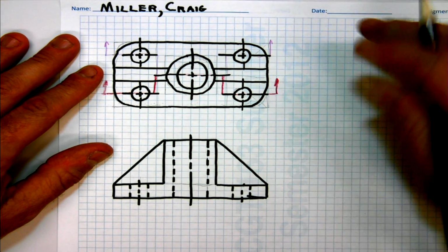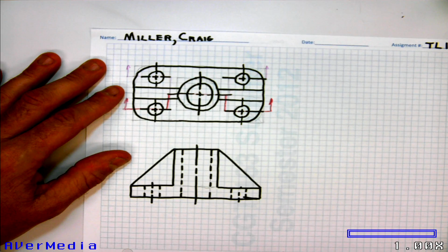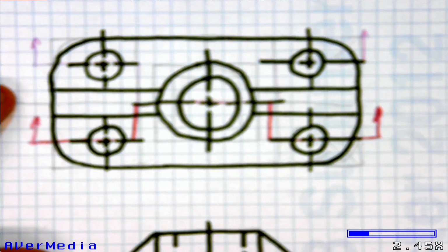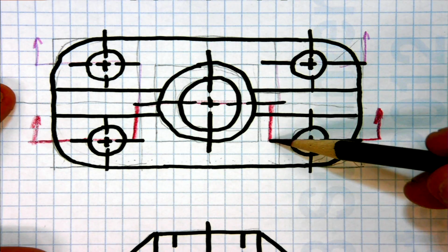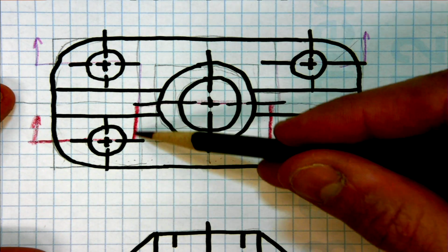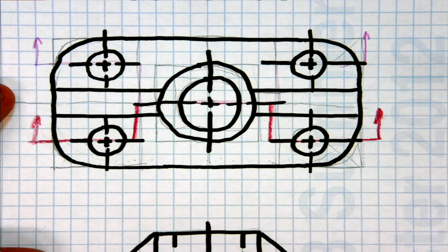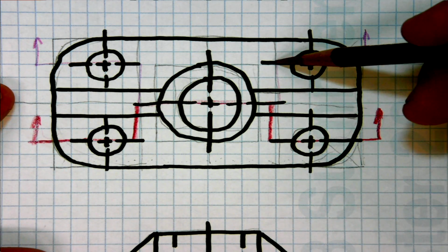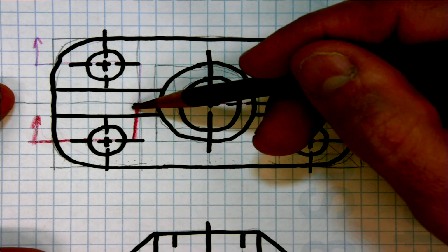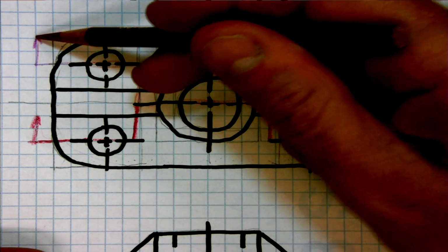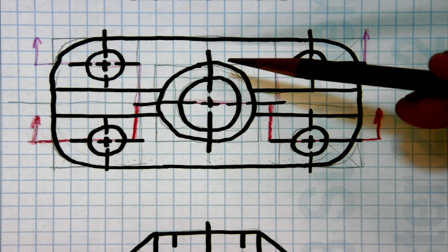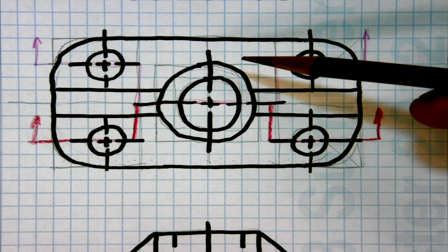Now you're going to get two radically different answers to this problem if you do this. So I'm going to zoom up here again so you can see the way I put these cutting planes. The red one goes here, turns, goes through the cylinders, turns, goes through here. Then the purplish colored one goes here, turns, goes through here, turns 90 degrees, and goes back through here. Now remember, since my arrows are pointing towards the back of the object, whatever is in front of that cutting plane will fall off.